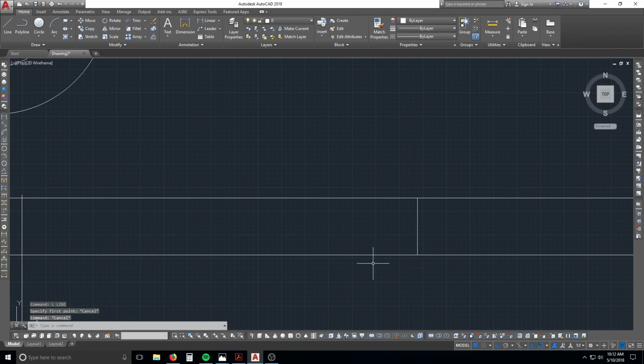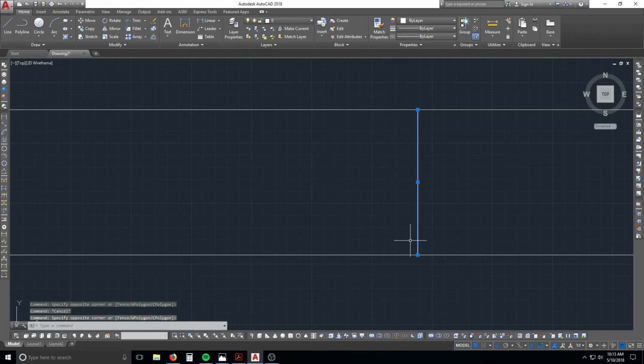Which brings me to a sidebar note here. Let's look at your OSNAP stuff. I apologize for not going over this earlier, it just dawned on me. If you type in OSNAP, it shows all the little symbols, like say that's endpoint, and you're like, wait a minute, it was just a triangle. Well, it's also dependent, because the end point of that line also intersects with the midpoint.